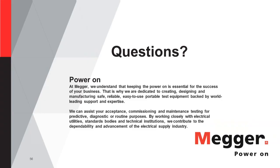I have one more question which says, how is equivalent phase time overcurrent pickup calculated in the example with the recloser? So equivalent phase time overcurrent is basically, as I said, for a line-to-line fault. If you're just having a feeder relay for the phase overcurrent, you don't employ the negative sequence component.